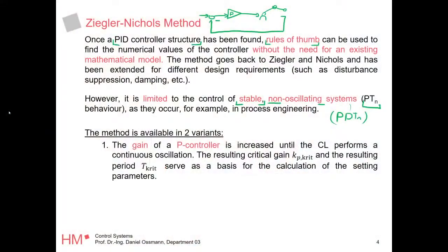You've seen it with the espresso machine. When you put the gain too high, you're actually getting unstable. And obviously there is exactly this one gain where it's not stable and not unstable, but your poles are on the imaginary axis. So you're neutrally stable. You're looking for that sweet spot, so to say. Okay, this is your critical gain. And the only thing you then do is, okay, instability in a linear sense will always be like, it will oscillate forever, right? And then you simply calculate the period of the oscillation, which is your critical period.